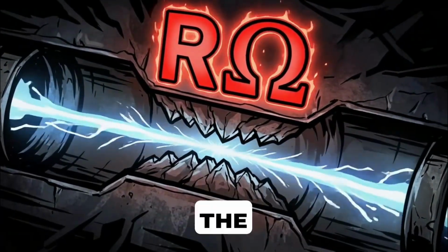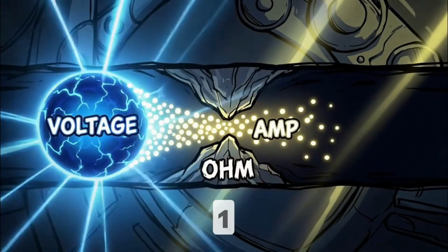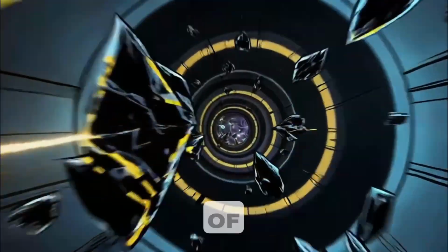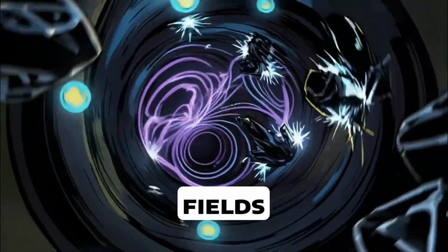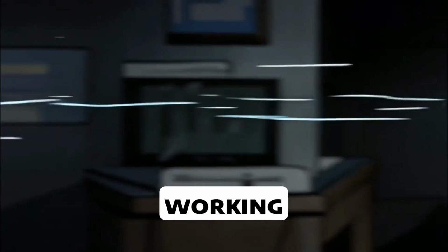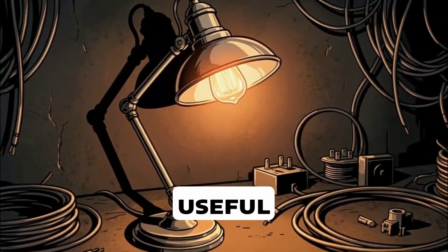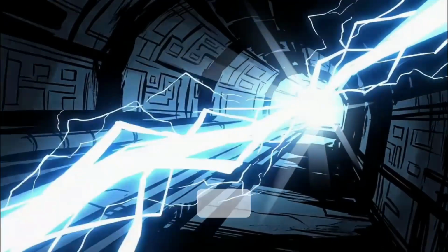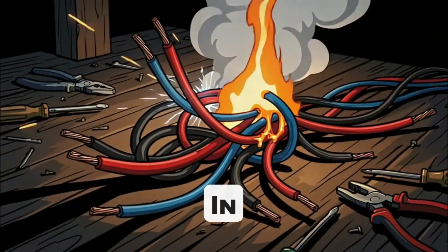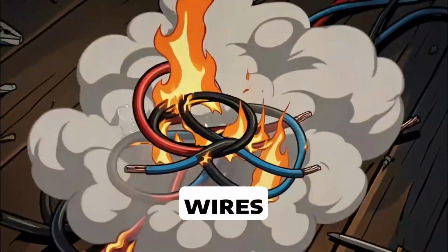The symbol is R and the unit is the ohm, shown by the omega symbol. The chapter states it simply: it takes 1 volt to push 1 amp through 1 ohm. Resistance is caused by the conductivity of the material, collisions between moving particles, and opposing forces such as magnetic fields or induced currents. In a properly working circuit, the load provides useful resistance and converts electrical energy into something useful such as heat, light, or motion. In a short circuit, resistance becomes very low and dangerous. Current can flow. In 120-volt building circuits, an unrestricted short can rapidly overheat wires and start a fire.